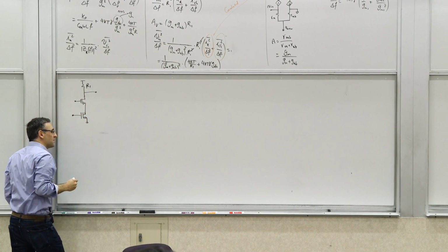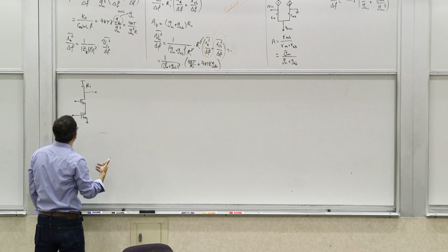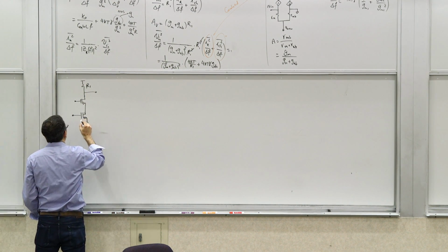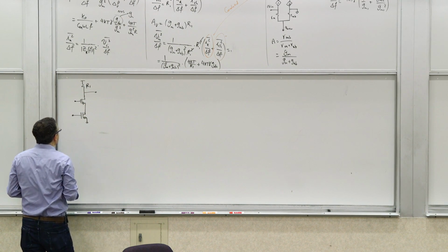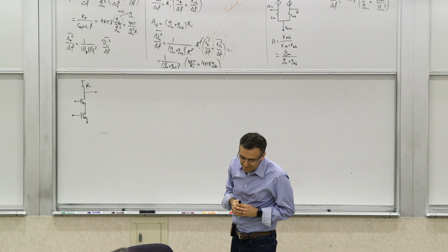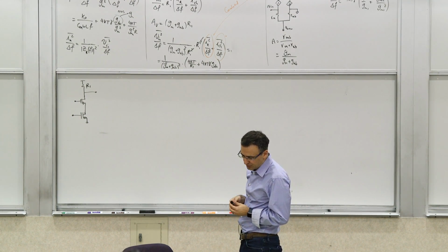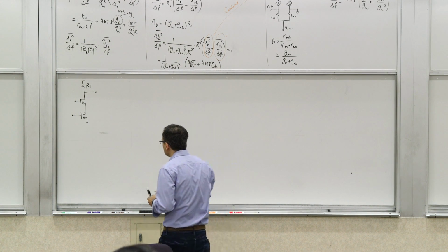It's the same way that, you remember when we started with talking about gains, initially we drew the small signal model every time, but eventually we learned how to do it in our heads. So we can do a similar thing with noise sources. We need to learn how to do that so we can gain some intuition about how to deal with those as we go. Okay, so let's look at this stage and see what happens to various noise sources in it. We have essentially the core ingredients of this discussion. I just want to make sure that we talk about them a little bit more explicitly.